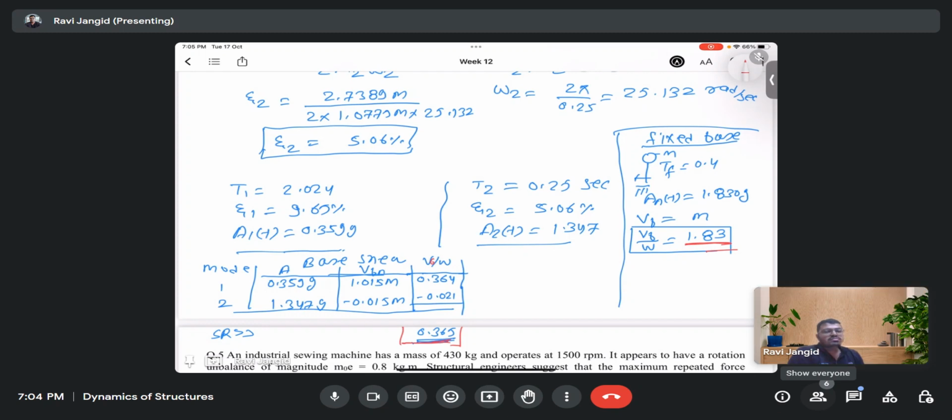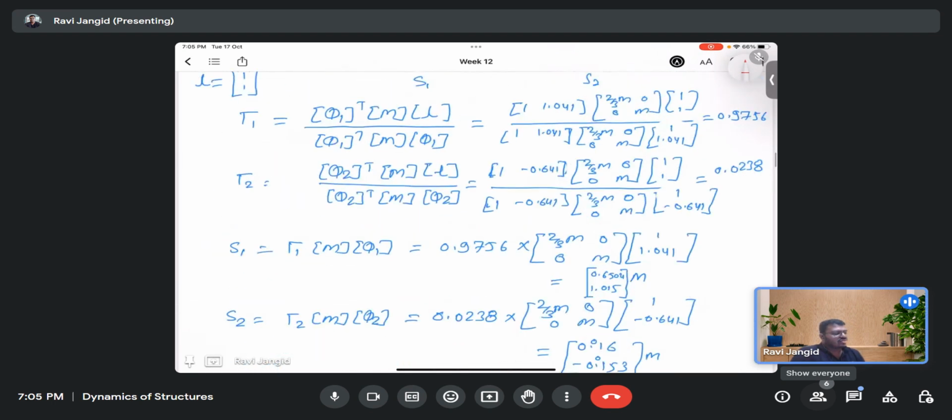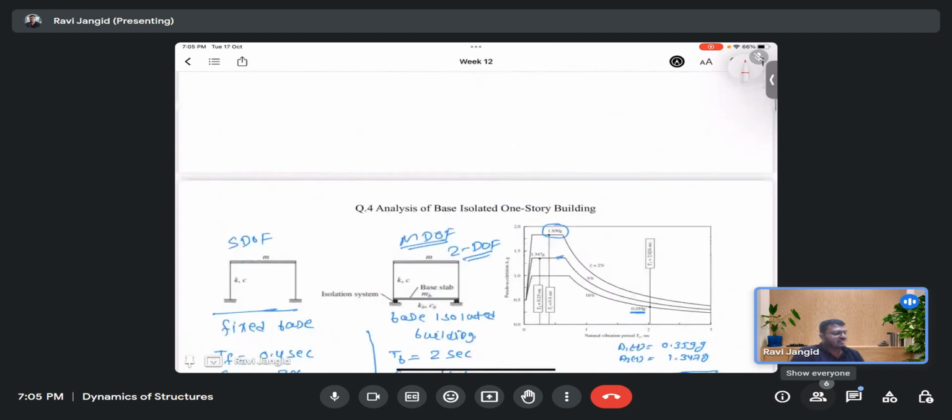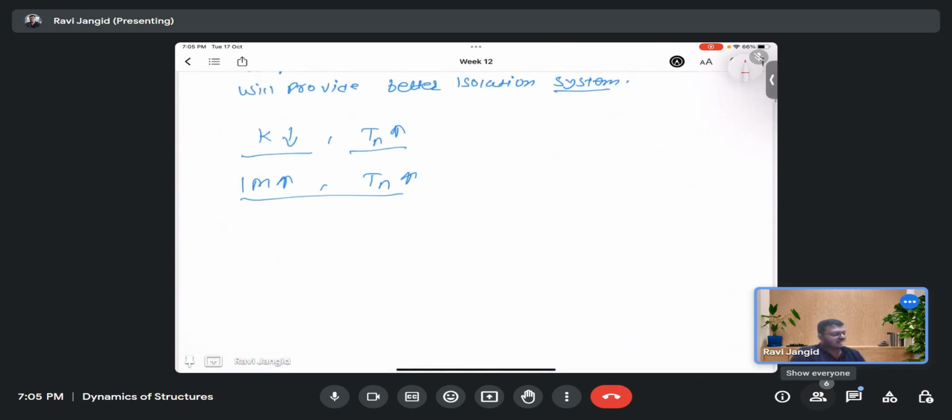I have a doubt. We are finding the base shear at the top of the base isolation, right? Yes. If you want to calculate at the bottom of the base isolation, that won't be useful, because that is the mat, and our columns start above that mat. We are interested in finding the shear in our columns. Can you please explain once how base isolators are applied to our buildings?